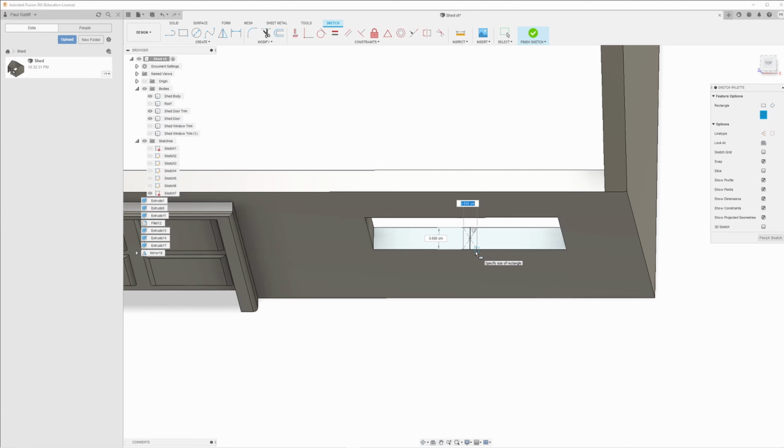So that is half a millimeter by 0.8 of a millimeter. I think, let's make that 0.06. That makes sure we can print it. Actually, let's just go crazy. Let's make it 0.08. I know that's a lot of exaggeration, but we're going to do that anyways. Now, first thing we want to do is get rid of the center line here. We don't need that any longer.